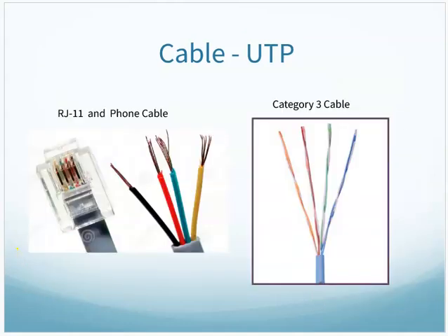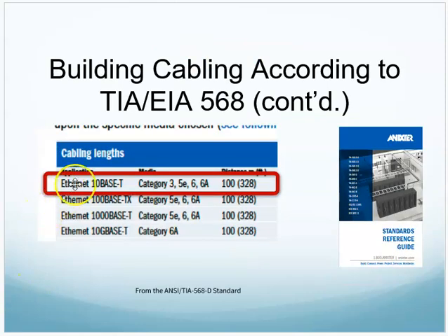When they did that, they were able to start getting more bandwidth through. Again, phone cabling here, you can get a handful of K, maybe 56K kind of thing. Once we wanted to start getting into 10 meg, they needed to start using cabling that was purposely twisted for the cancellation purpose, and that's where Category 3 comes along. And that was capable of 10 meg.